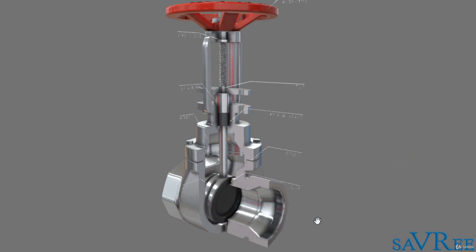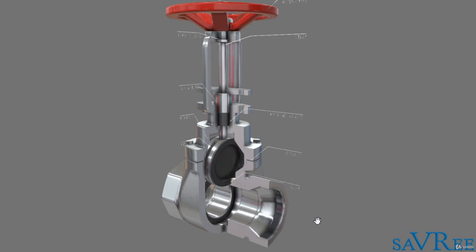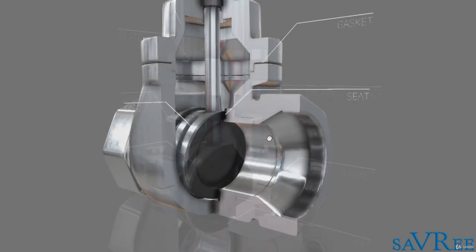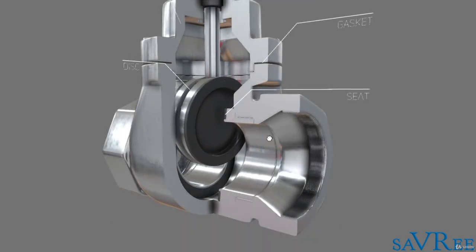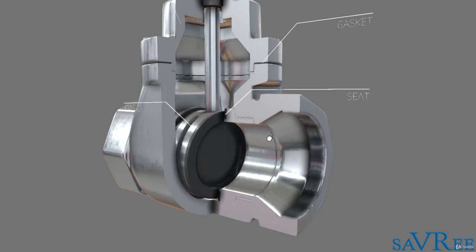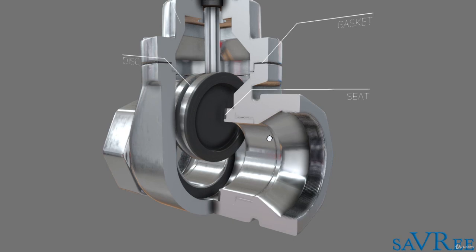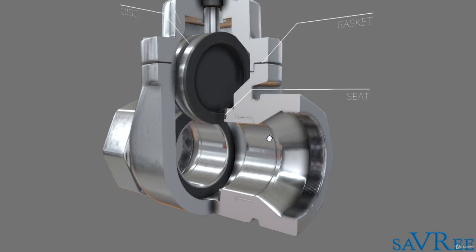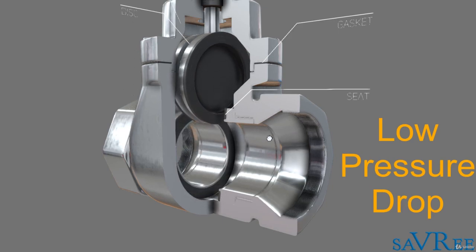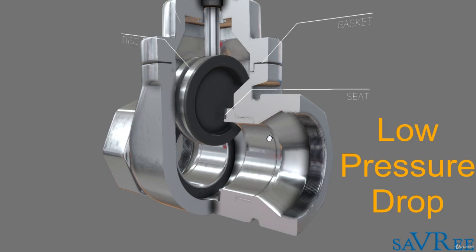I'll push the play button and then we can watch the gate valve operating or actuating. So now it's in the closed position and it's moving up to the open position. You can see that when the valve is fully open, there is very little resistance to flow passing through the valve. Now this is very good because this means we're going to have a very low pressure drop. So as the fluid or the gas is flowing through the valve, it's going to encounter very little resistance and we'll have a correspondingly low pressure drop.